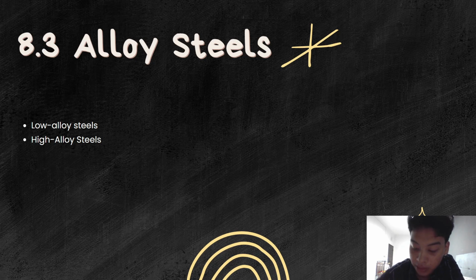This is not a hard and fast rule, because some steels with alloying slightly above 8% are sometimes referred to as medium alloy steels. Ultra high strength nickel steels, high strength low alloy or HSLA steels are designed to provide better mechanical properties and/or greater resistance to atmospheric corrosion than the conventional carbon steels. They are not considered to be alloy steels in the normal sense because they are designed to meet specific mechanical properties rather than a chemical composition.